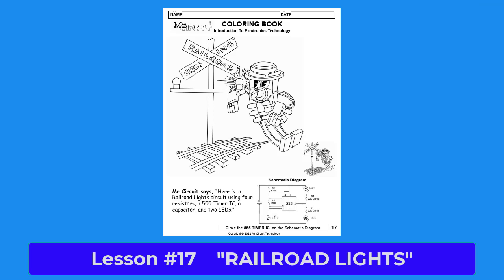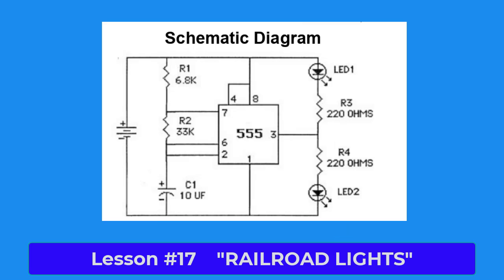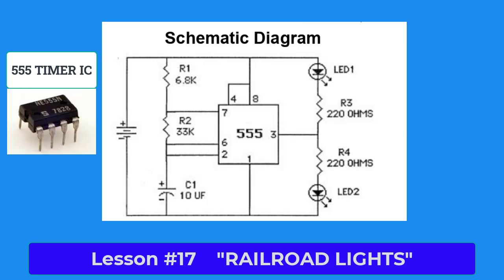The schematic diagram for the railroad light circuit is shown on the lower right-hand side of the page. It has some of the schematic symbols that you were taught in lessons 1 through 11 of the STEM activity book. You may remember from lesson 11 that a 555 timer IC can be used to make LEDs blink on and off. This circuit was designed by engineers using the 555 timer IC to make LEDs blink alternately, like on a